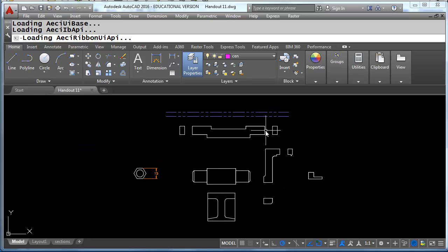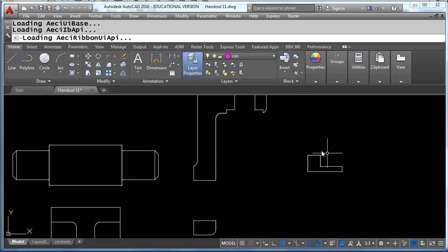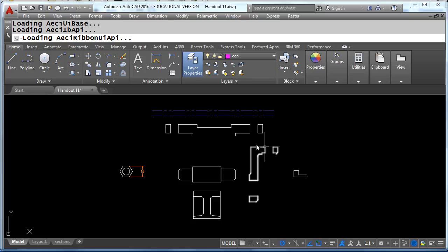Notice the axle and the top plate, I've already taken out the holes for where pieces will be assembled together with that bolt nut assembly before I made those into blocks. The bushing, I only needed this one area here. This will be part of the pattern that I'll repeat on the other side. The main reason for turning these items into blocks is to keep them easier to work with.